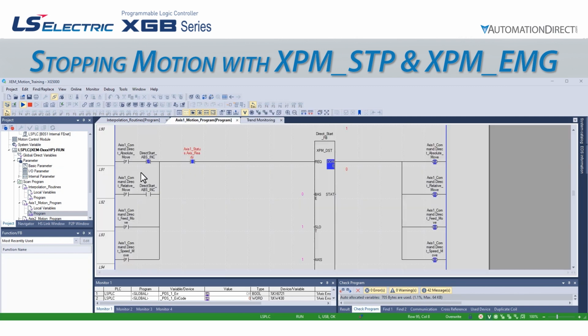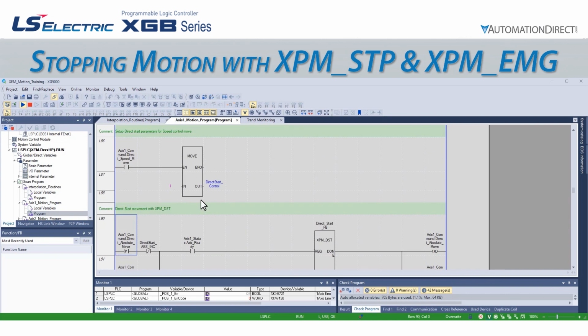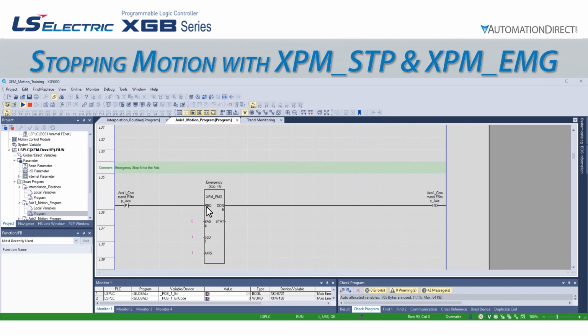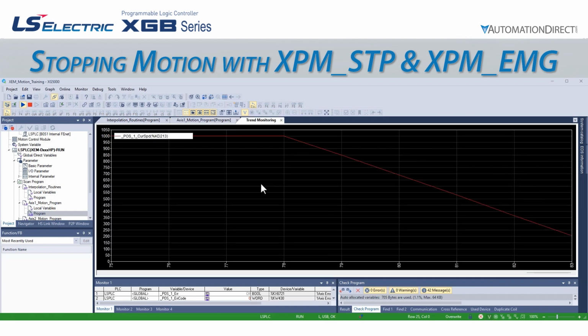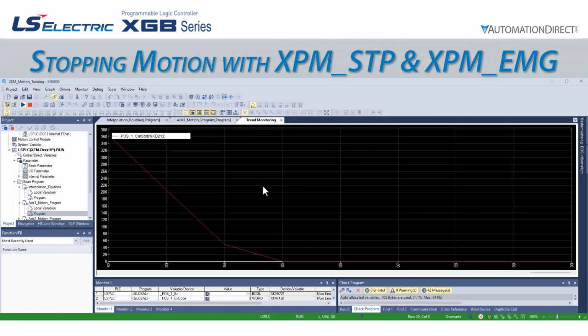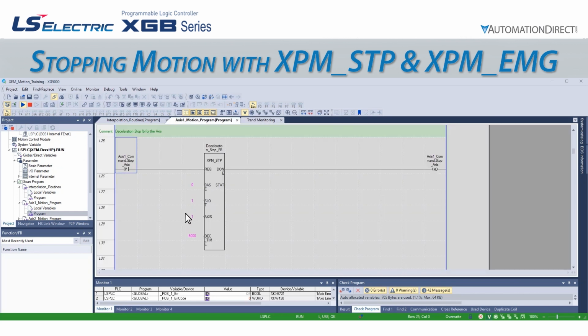Let's trigger our direct start and look back at the trend. We see that the axis accelerates up to 1,000 and then remains at constant speed. Let's go to line 25 of the code and trigger our decelerating stop. If we look back at the trend monitoring, we see the speed curve drops back to 0 over a 5-second interval as expected. Perfect.